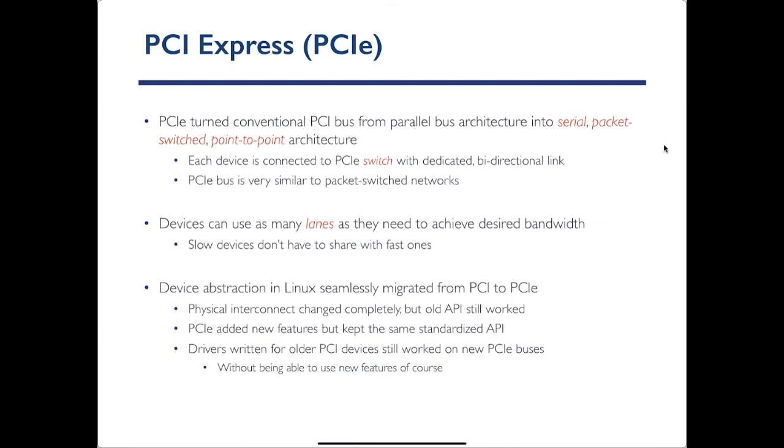I mean, if the device wants to directly communicate with the memory. Otherwise, if the communication is by the CPU to the device, then we just use this in and out, right? So the CPU, for example, reads some data from memory, puts it in a register, and then uses out or in to send or read the data from the device.